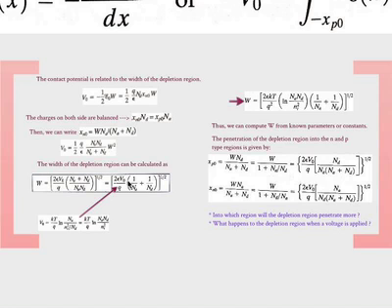Basically, when V is positive, and we'll define this as P and that as N, the positive terminal goes to P, the negative terminal goes to N, so V is positive. When V is positive, you can see the depletion region decreases because this potential decreases. You're decreasing the contact potential. When this V becomes negative, it's reverse bias. This whole thing increases, W increases, the depletion region increases.